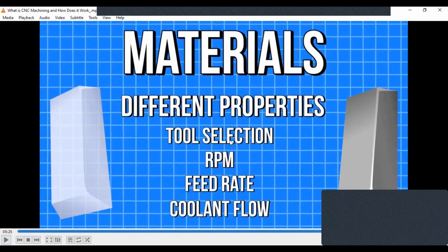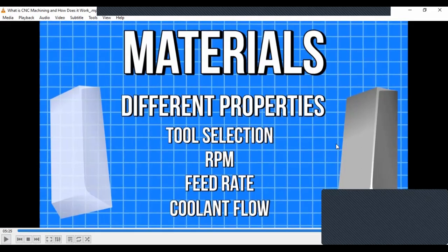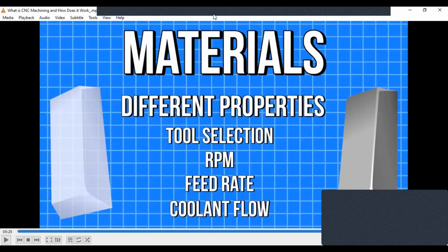You see all of these, as the material changes, you have all these factors changing, isn't it? The tool will change based on the material. If the hardness of the workpiece is high, then you have to have a tool that is harder than that. Only then can you machine that, right? Common sense. Also RPM, with how much speed the tool is moving, or if it is a turning process, how much RPM the workpiece is turning.